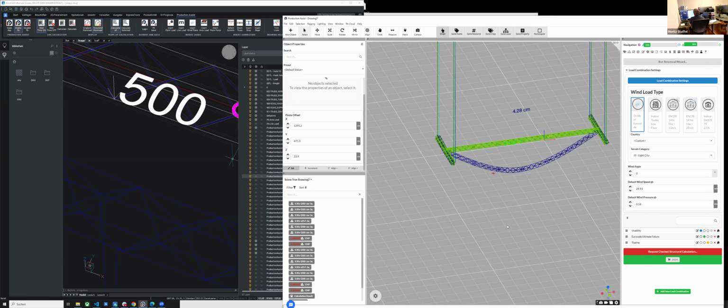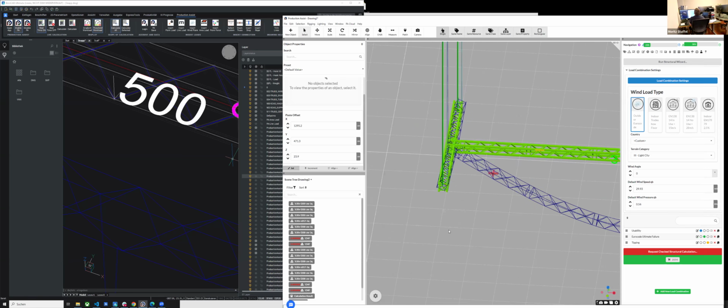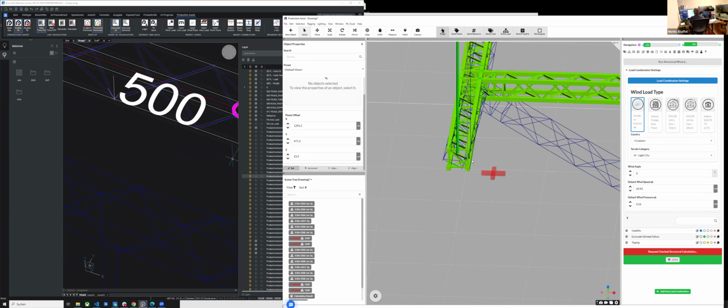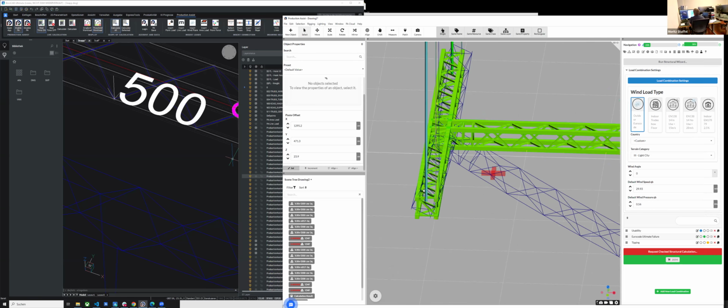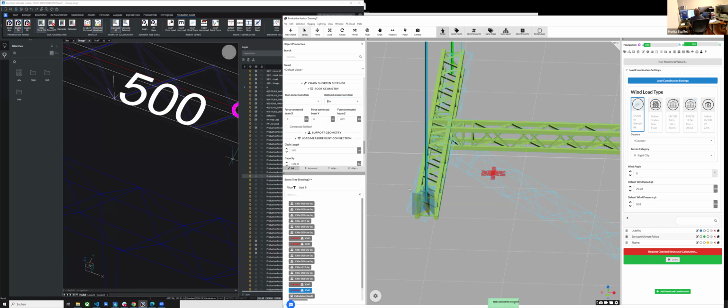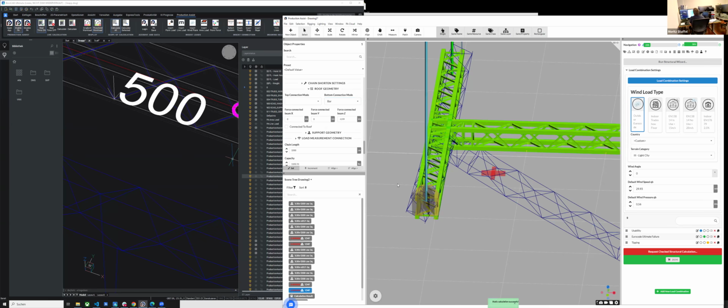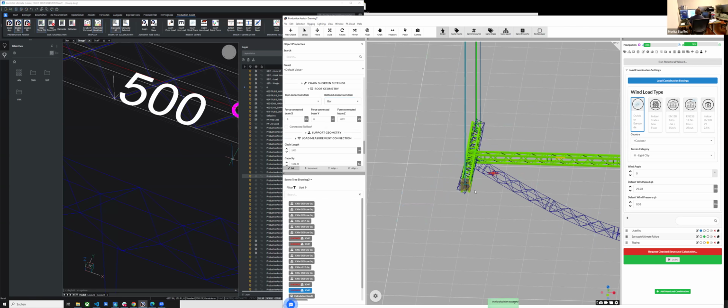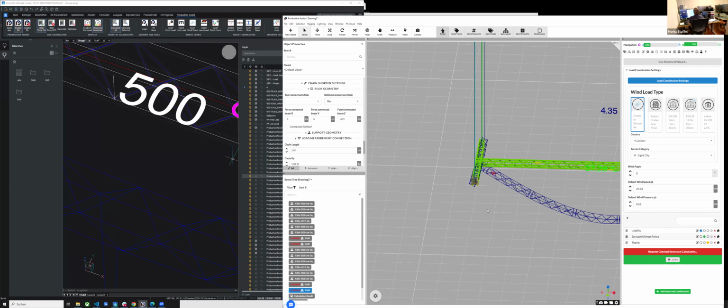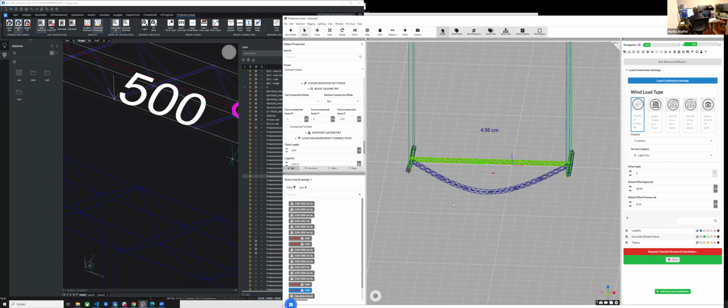What this also can do is that you can define how the sling method is attached. So currently, when I'm clicking on the hoist, this is set up to go to the roof geometry to use a single tube. You can also set it up to use a bar, and then it uses a bar between these two things and slightly changes the calculation. So the effect of how you sling the truss can now be calculated using this feature.